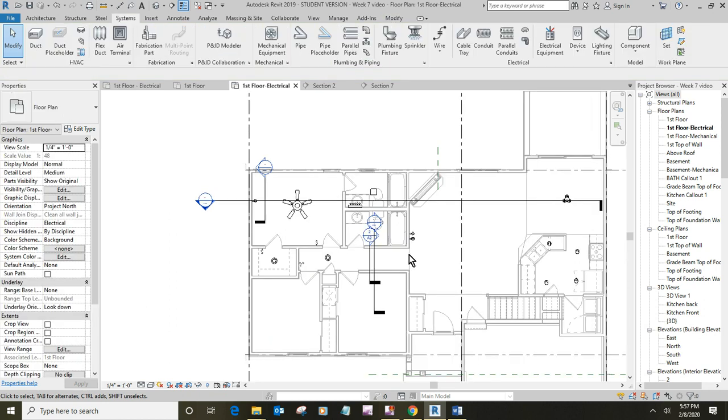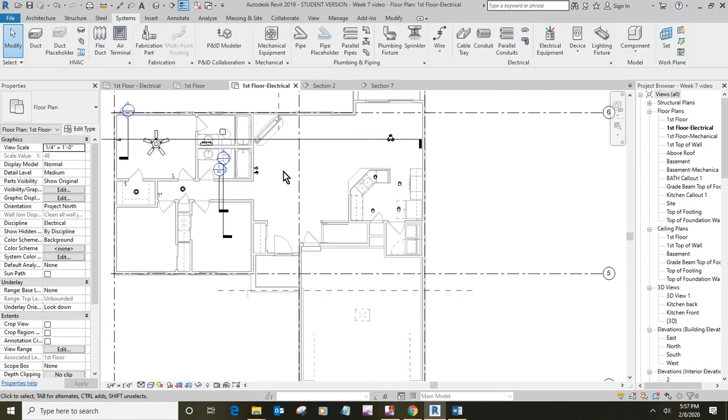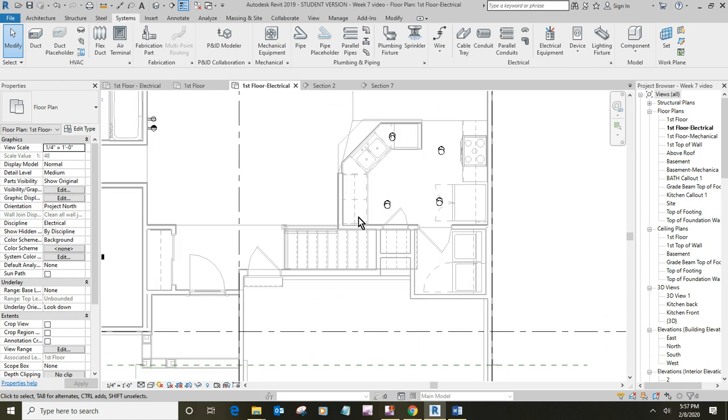So you got those. You're going to need outlets. You're going to need ground fault outlets in the kitchen, and the ones here above the countertop, of course, need to be at typically 4 feet or so. So let's go back to here.